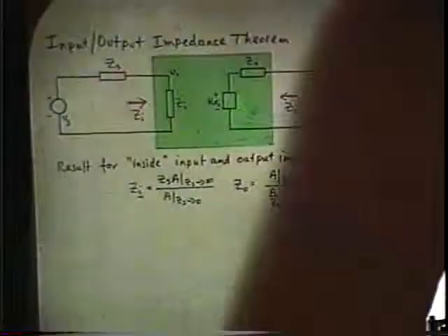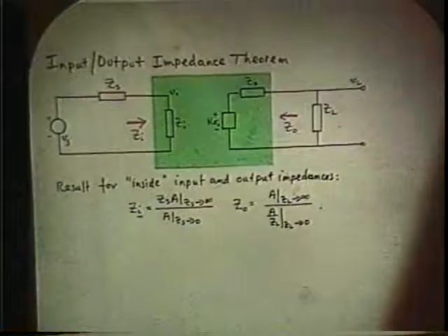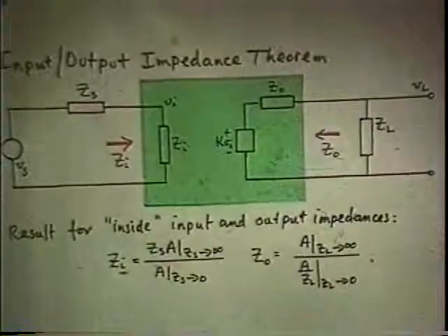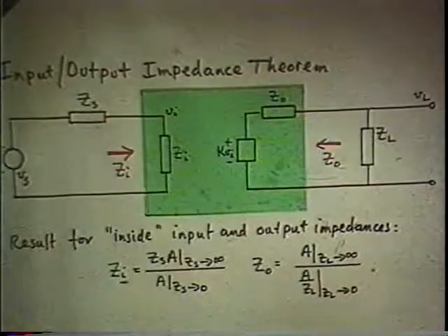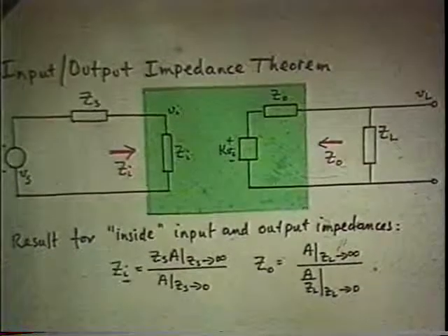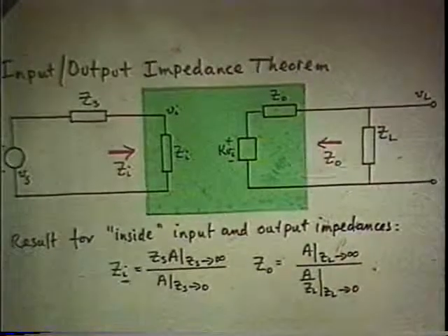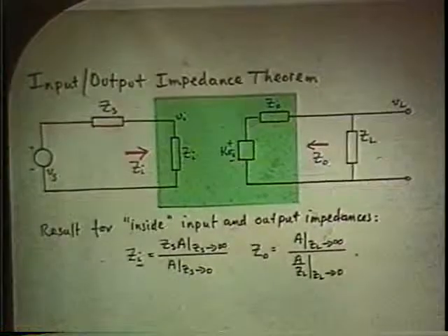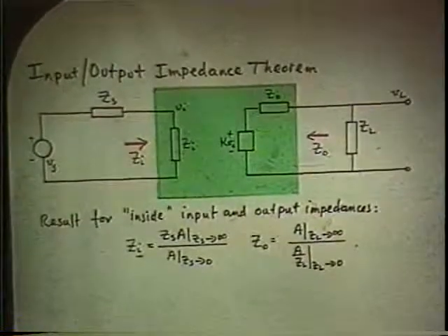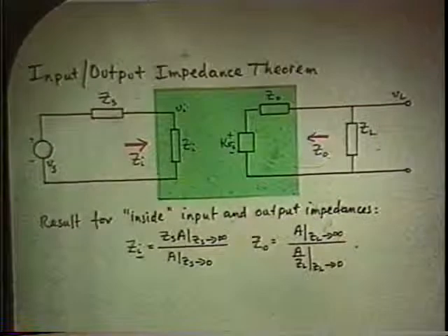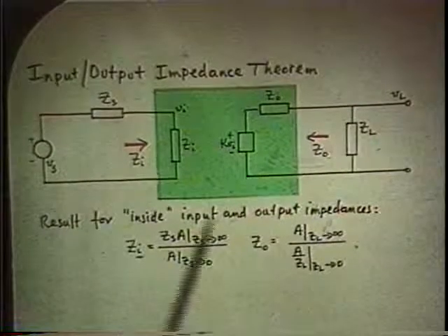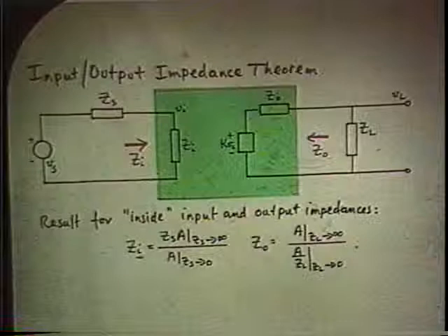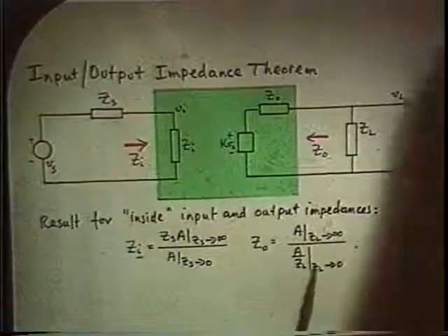And the trick is, you avoid repeating the parts of the analysis that are the same as the voltage gain by using the voltage gain answer to find the other two transfer functions. That's how you use the work that you've already done. You use it in the form of the first answer.